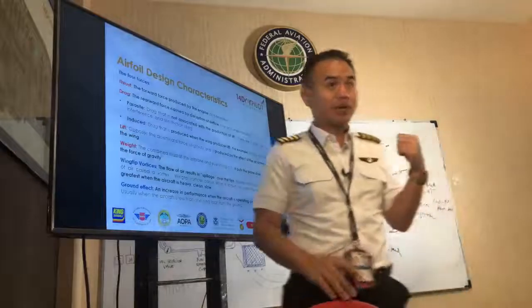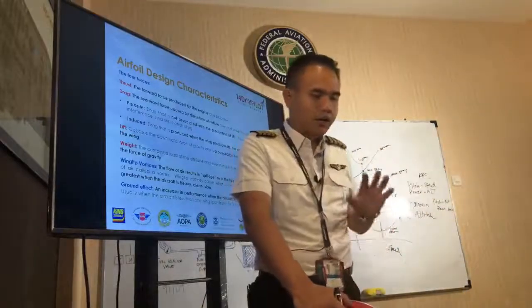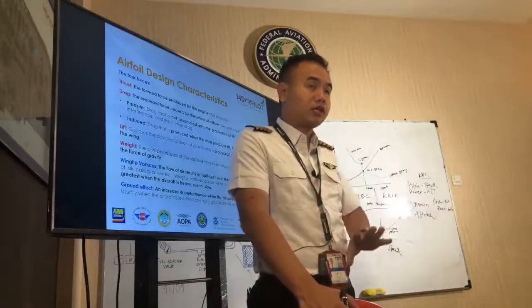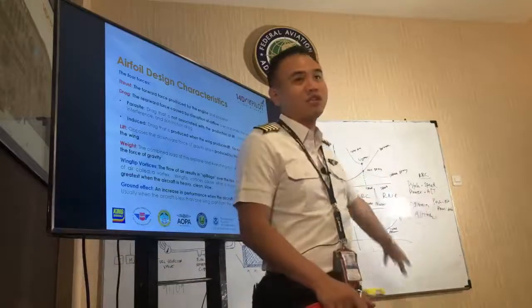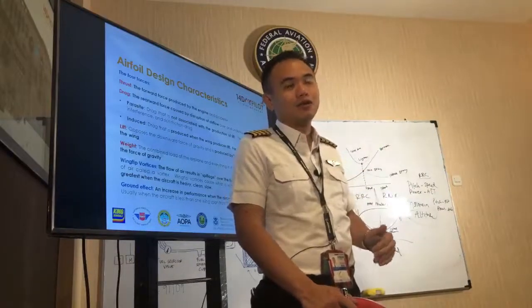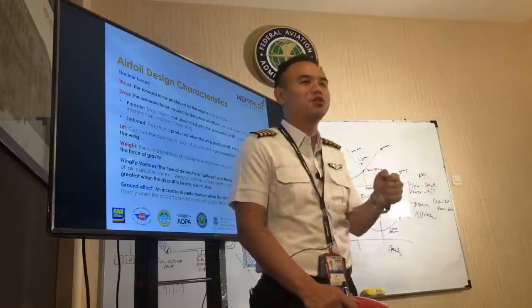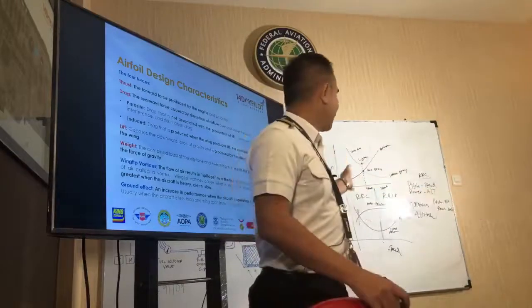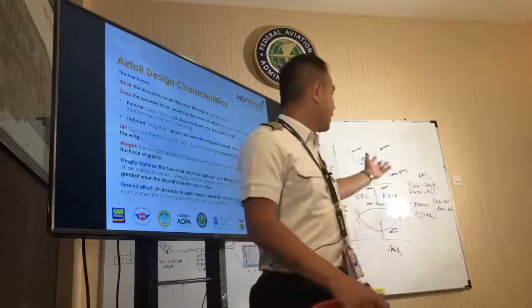This is really deep understanding. A lot of people think power for altitude, pitch for airspeed. Yes, that happens in the region of reverse command, because you need power to maintain the altitude. You cannot maintain the altitude with only the pitch. You need power.